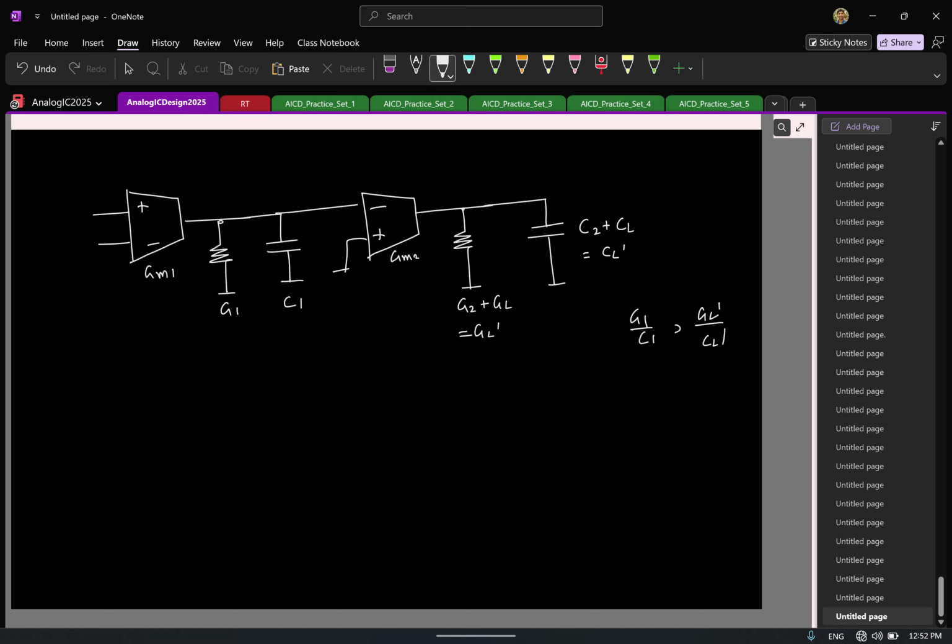Right? So if I again sketch the root locus quickly, in the open loop, the loop gain has two poles which are close to each other. So the closed loop poles will do this. But ideally, for a good settling response, where do you want the closed loop poles to lie? On the real axis, right? As such, if you take this and put it in feedback, if it has a large enough gain, your closed loop poles might lie somewhere here, on the complex plane. So you might have a lot of ringing. So let's see what we can do to correct that.